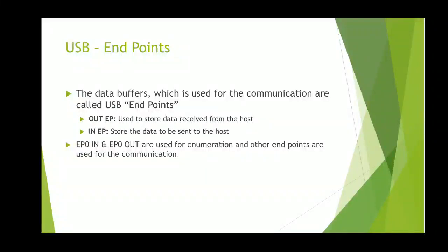Now let's go through the term endpoints. Endpoints are nothing but the data buffers which are situated in the peripheral device, and these endpoints are used for the communication between the peripheral device and the host machine. There are two types of endpoints: in endpoints and out endpoints. The out endpoint is a data buffer which is used to store the data received from the host machine, and the in endpoint is the data buffer which is used to store the data which is to be sent to the host machine.